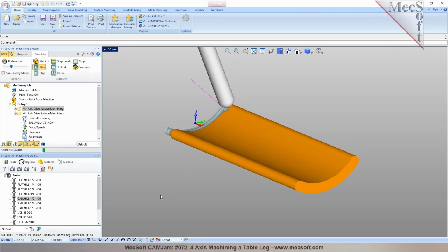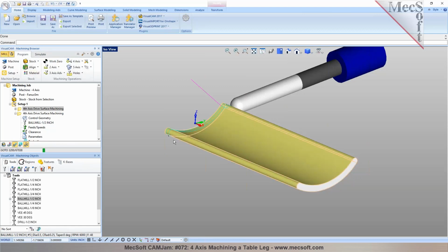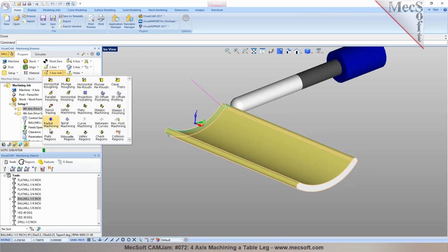That's interesting. Now these methods, the 4-axis methods, are available in the Expert and Pro configurations. I would recommend the Pro configuration, as you can take advantage of all of the 3-axis advanced methods as part of indexed 4-axis. That means when you do rotate table setups and program an indexed operation, you can use all of the advanced 3-axis methods like re-roughing.